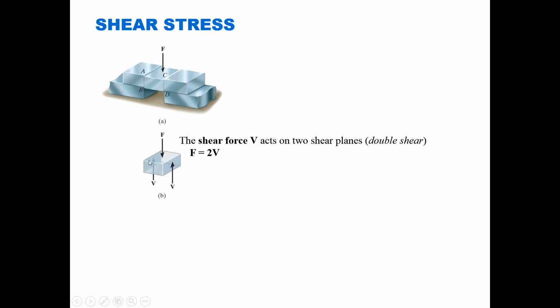Okay, so we call that double shear. We're going to find with some examples here in a moment the difference between single shear and double shear and how that affects the calculations a little bit. Okay, so you always have to visualize the failure condition and understand the difference between single shear and double shear.